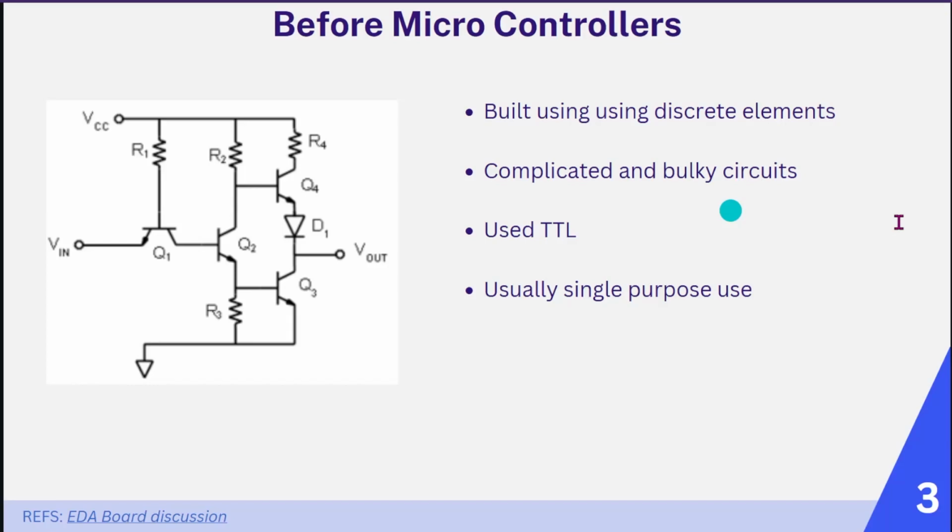One major limitation is its power consumption. TTL gates consume more power compared to other digital technologies such as CMOS, which can lead to overheating and reduced battery life in portable devices. Another limitation is its susceptibility to noise and voltage spikes. TTL circuits are more sensitive to noise and voltage spikes than other digital circuit technologies, which can cause false logic states and errors in data transmission.